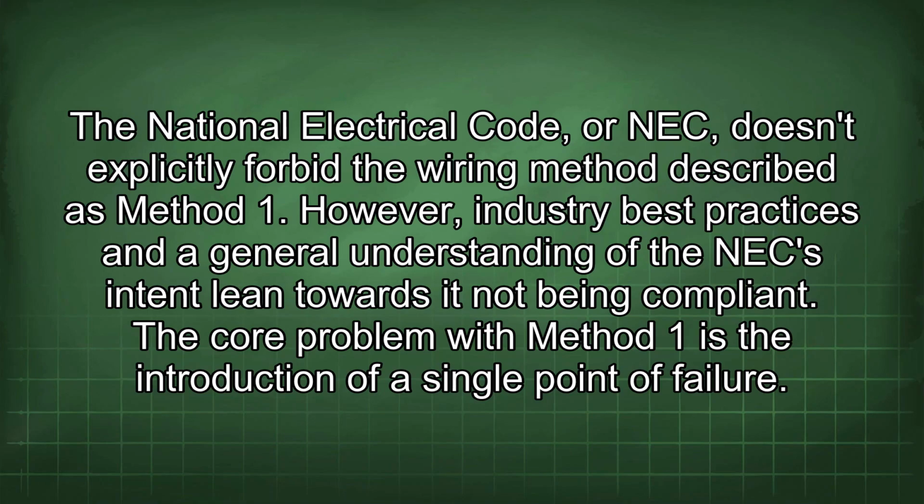The National Electrical Code, or NEC, doesn't explicitly forbid the wiring method described as Method 1. However, industry best practices and a general understanding of the NEC intent lean towards it not being compliant. The core problem with Method 1 is the introduction of a single point of failure.